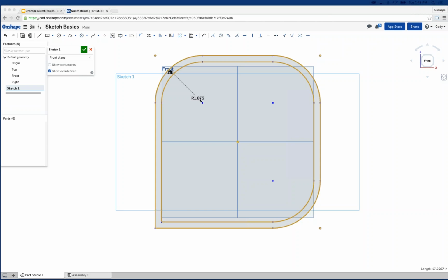Now, if everything is in one sketch, it really doesn't make a big difference, because I can then fillet every edge in the sketch. But when we start talking about 3 and 4 and 10 and 100 features, and I want to fillet 5 edges from other interrelated features, I'd probably use a feature level fillet. If everything's in that one sketch, I'd probably use a sketch level fillet. But it's important to understand that even experienced CAD users will sometimes disagree about that option. So it sometimes can boil down to a matter of preference more than anything else.